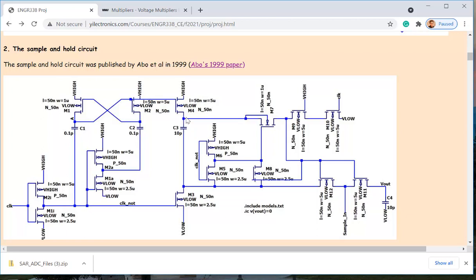So what's going to happen to this point? The charge on the caps has no place to go. Keep in mind, it's already disconnected from the top and bottom, like a floating VDD over here. Floating VDD right now means, because it was dragged to the ground, imagine that it's VDD and 0 volts, and you cannot change it. It has no place to go. It's always VDD and 0. The amount of voltage drop will be VDD.